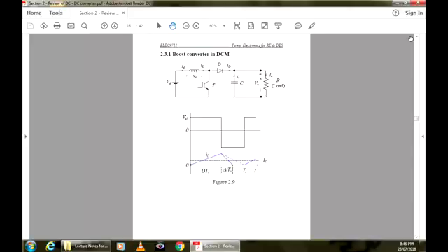When you turn the switch on, there is current flow here. And the diode is off because positive voltage here, negative voltage here, and 0 voltage here means the diode is reverse biased and it is off. So when you have switch T on, this diode is open circuit and the load current is supplied by this capacitor alone. There is no contribution from this DC side when you switch it on.